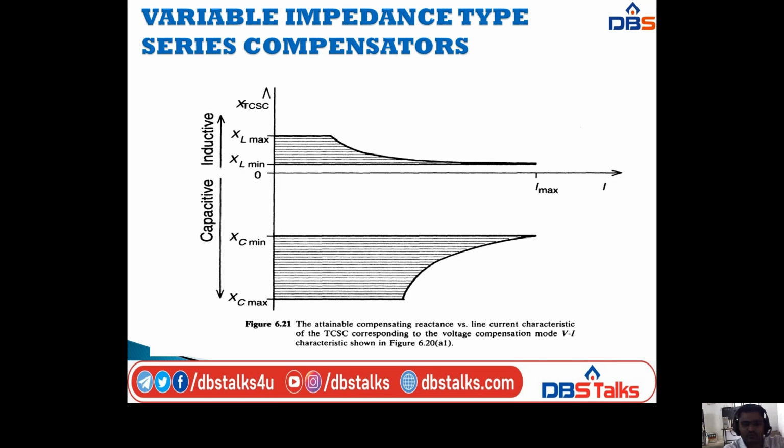So in this one we have two regions, capacitive and inductive. The inductive region is in the positive half and the capacitive region is in the negative direction. We have the XC maximum and XL maximum, and XC minimum, XL minimum, and we have the capacitive reactance of the TCSC scheme. Okay, like that we are taking.